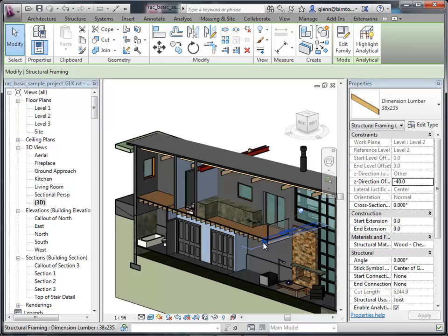You can count the total number of 2x8s that are in here and start thinking about what our materials quantity lists have to look like. We have all these doors and windows, and we can start thinking about door and window schedules to add all that information up. Let me show you how that works too, because that numeric side of it is just as important as all this graphical fun.